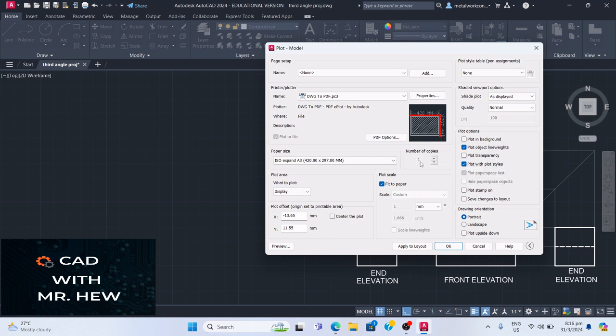If you want to print it on the 17 by 11 paper, the equivalent size to that is the A3 paper, metric paper, 420 millimeters times 297, which is the length and the width. Here it is shown right there in red, right? So it's not landscape. We're going to click landscape here nevertheless, right? Then we're going to center the plot on the paper.